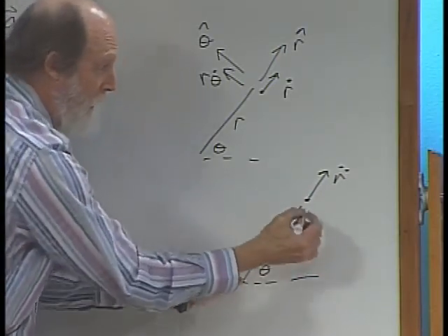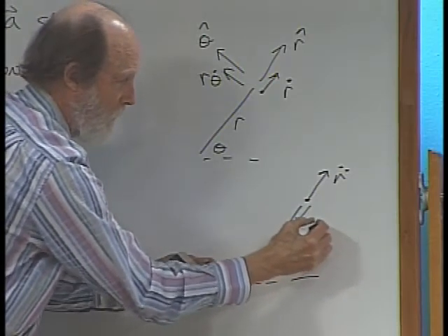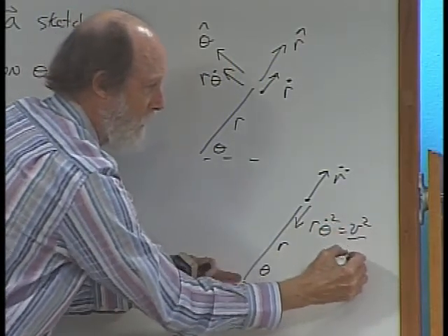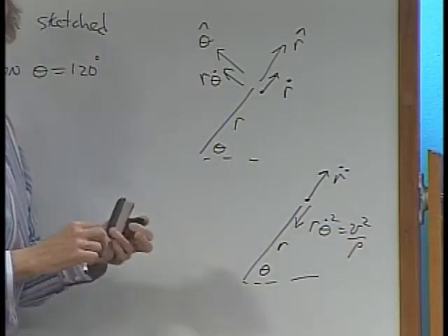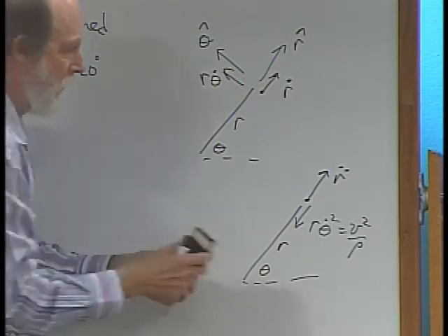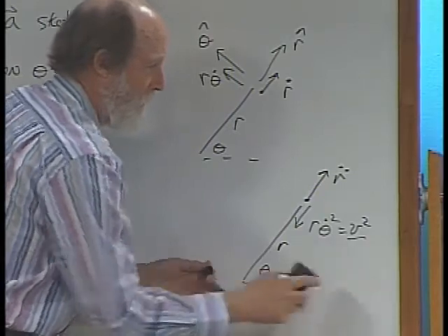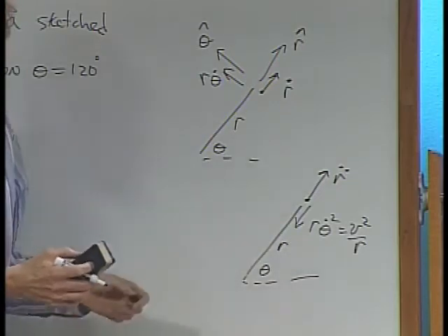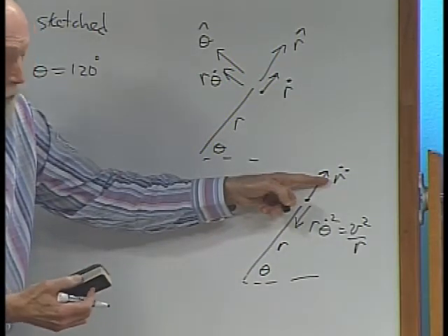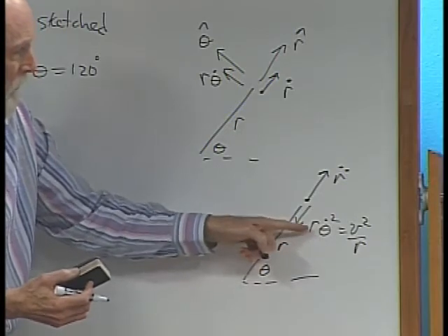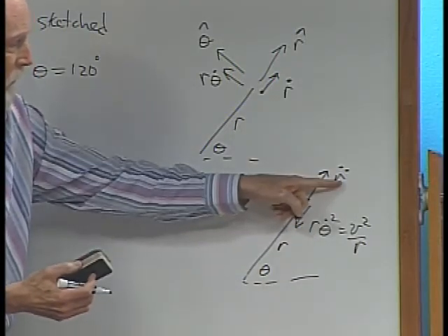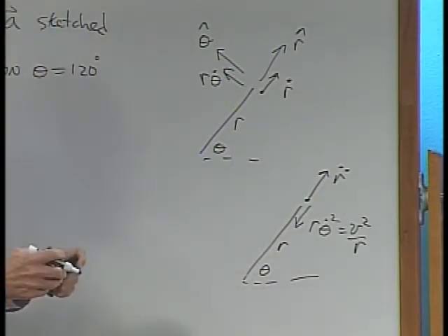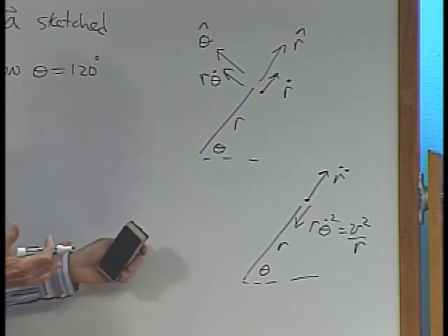So it may not be that, but there's going to be another term pointing back this way, which is one that you've seen earlier, r theta dot squared or a v squared over rho. And actually, that's going to be a v squared over r in this situation, because this is the term that's pointing back towards the pole. So the combination of that telescoping effect outward and this pseudo kind of normal term pointing back towards the pole, the addition of this minus this is going to be that radial one. Did that help you remember this stuff a little bit?